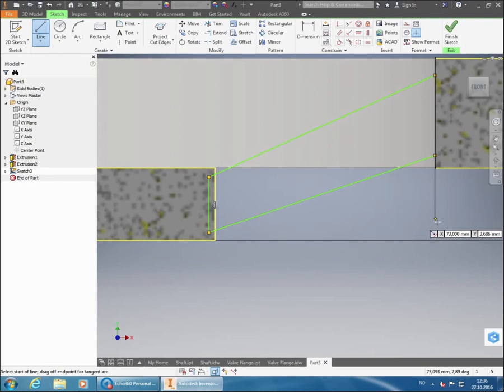Now, in order to get this as perfect as possible, if you're doing this from scratch and you don't have a compendium to look at, it is usually necessary to do the extrusion and then go back into the sketch, fix a little bit on the distances that you are going to put in here, and try again, see how it looks, and then back and forth a little bit until you get to adjust it perfectly. Luckily for you, this is something I did this summer when I created the compendium, so we don't have to go back and forth now in order to create this.